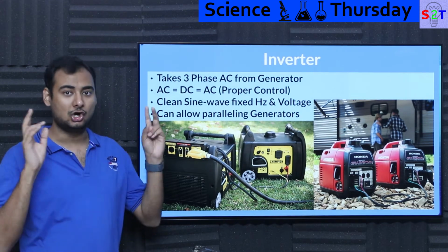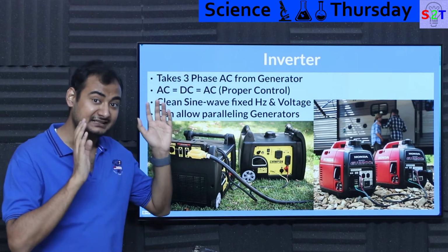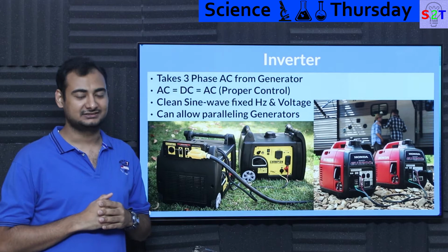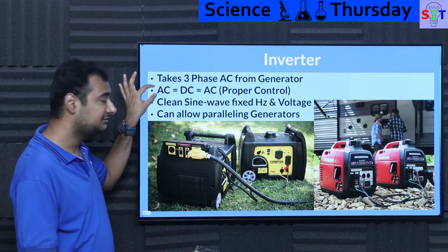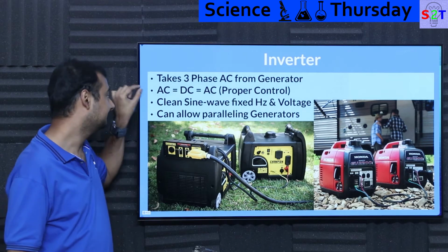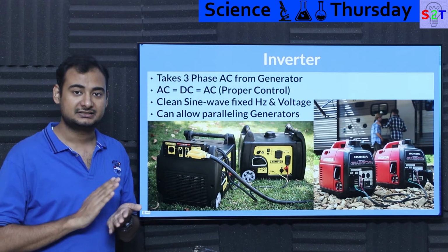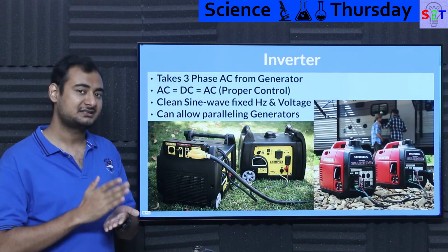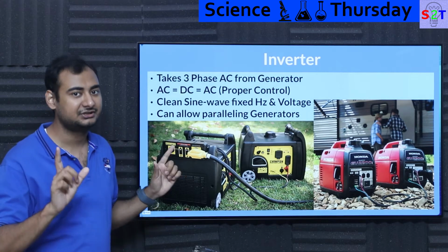And in the case of, let's say, ultra high voltage DC, people generally take 3 phase, make it into 6 phase, and then they have 12 pulse rectifiers. So they have really clean DC. So the same happens here. Your BLDC output is AC. Now that AC goes into the rectifier, gets smoothed out with the capacitor and inductor, and then you create a new AC. Basically you are utilizing the inverter circuit there.